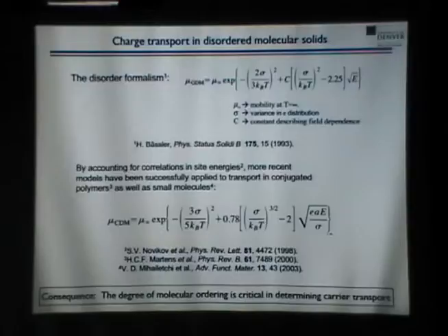So there was a question before the break about what happens when you take these solar cells and put them outside. Are they going to heat up? The answer is yes. And typically, if you put a solar cell on the roof, it will reach something between 55 up to 60 degrees centigrade. If you go into the desert, you might see 80 degrees centigrade.